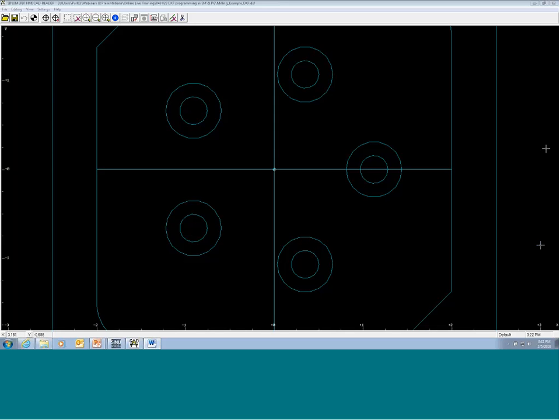We talked about this briefly, but just to revisit it, can I import 3D files? A lot of guys are certainly trying to do 3D surface work. And again, back to what I said earlier in relation to a DXF file, DXFs only support 2D, so no, this will not support a 3D scenario. But in the same token, if I had a 2D profile in a YZ or an XZ orientation, I certainly could pick that feature and apply that to one of our milling cutter paths and maybe loop it over. So you can do some pretty tricky stuff if you want to play around with the 3D shape. But if you're truly talking about a true free-form three-dimensional shape, you would need to use a CAD/CAM package to support that kind of geometry.